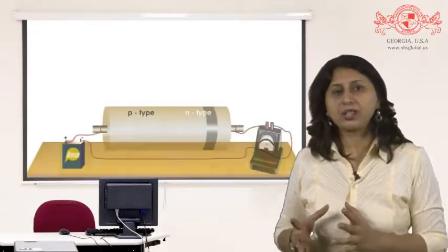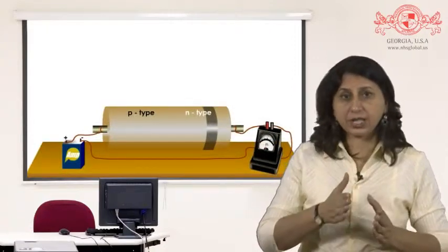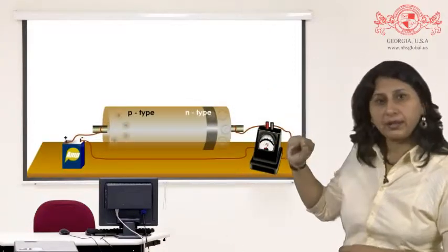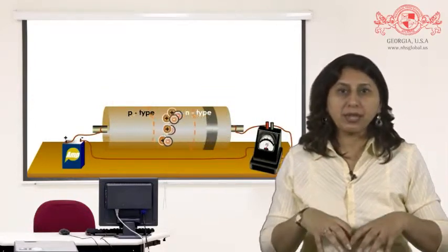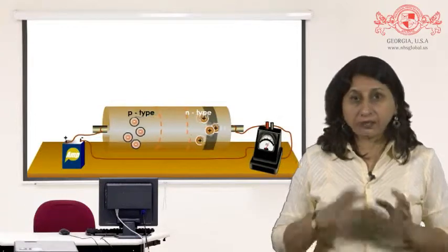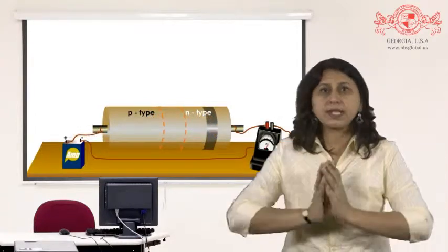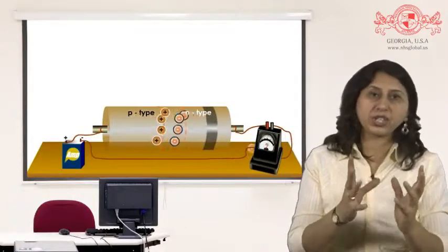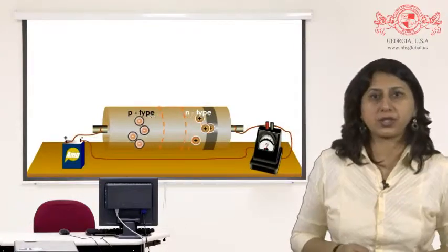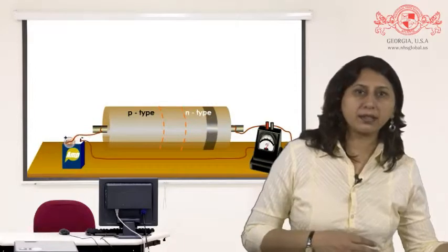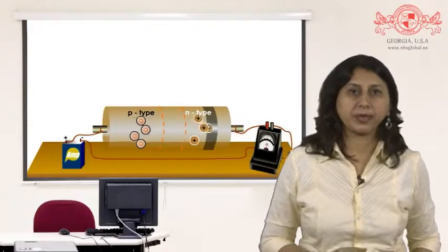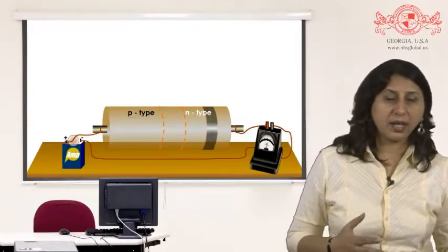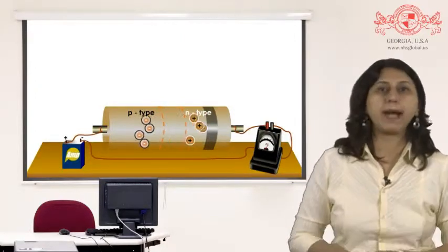Current flows through the junction if the p-n junction is connected to the battery as shown here. Holes and free electrons enter the depletion region due to repulsion at the respective terminals. The reduction of the potential difference causes a large number of majority charge carriers to diffuse across the junction. Holes travel to the right and electrons to the left, constituting a current in the same direction. Thus, the p-n junction allows current carriers to flow through it if the junction is forward biased.